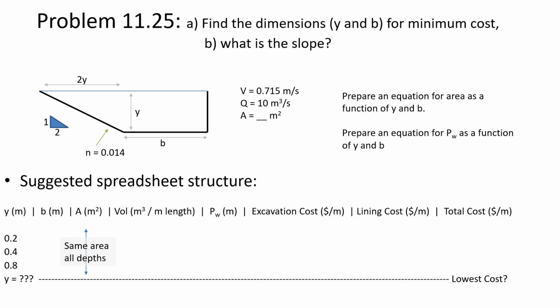Later in the semester when we do channel design, we'll talk about how much freeboard you want to provide for things like wind-driven waves. If you're going around a curve, there's super elevation of the water, safety factor for additional capacity. But here, just make it tall enough and assume that the water's just about to spill out of the top.